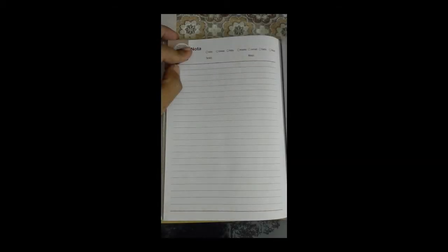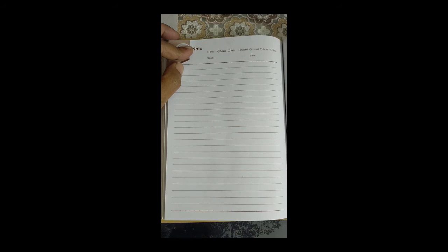Sample problem 4.12. Air enters a compressor and is compressed adiabatically from 0.1 MPa, 27 degrees Celsius to a final state of 0.5 MPa. Find the work done on the air for a compressor isentropic efficiency of 84%.